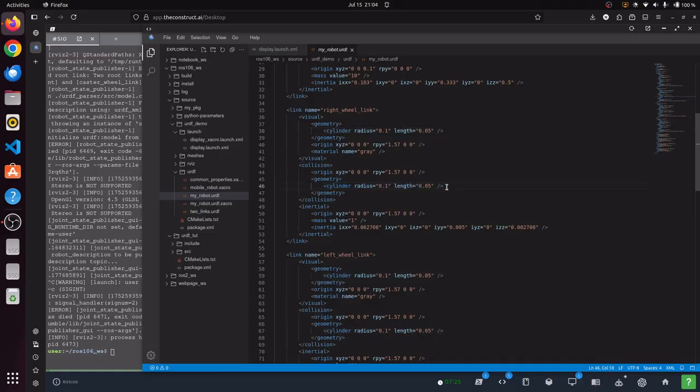There's one more improvement in my code. When you're making wheels and specifically collision models of them, you can sometimes replace cylinders with spheres, because when you simulate in a physics engine, if there are more points of contact with the ground, it can sometimes behave weirdly. So one thing people sometimes do is change this cylinder to a sphere of the equivalent radius.